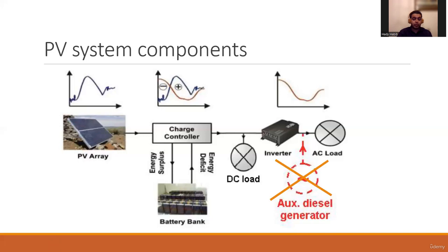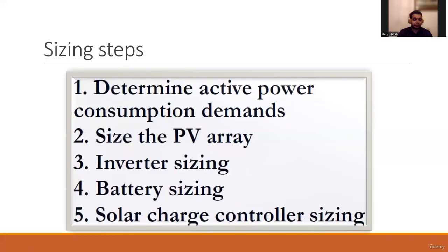So we will be depending on the PV as the source of electricity production from the sun, and the battery storage system that we are going to store the energy in while we have excess energy, and it will feed the demand when we have a reduction in our generation to feed our consumption.